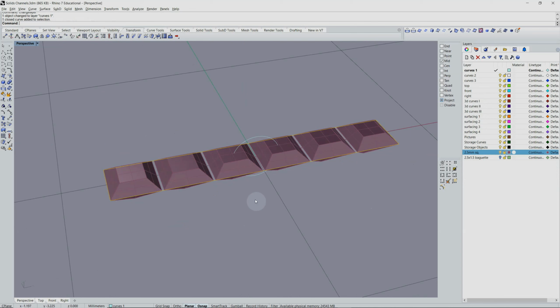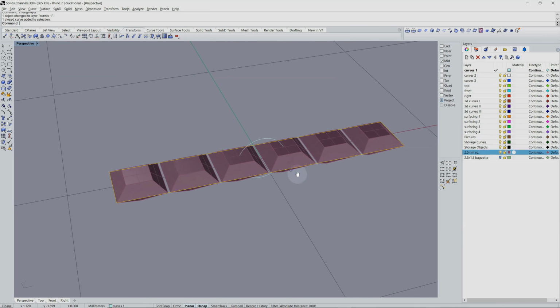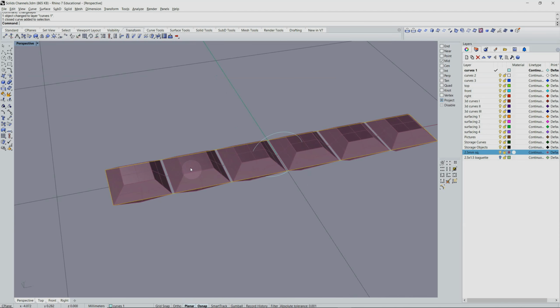And now I need to offset this curve to establish the outer boundary for our channel setting. The wall thickness for a channel setting is a technical as well as aesthetic consideration. You don't generally want them in excess of 1 millimeter in thickness, nor do you want them to be less than 0.6 of a millimeter in thickness. The thickness that you decide upon should be based on the size of the stones that are going to be set. For stones this size, 2.5 millimeter calibre, a wall thickness of 0.75 millimeters would be appropriate.